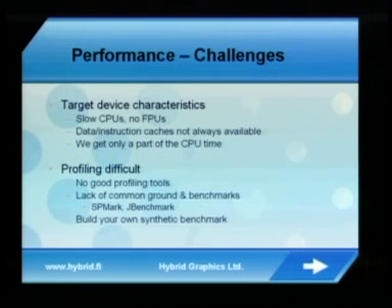The things that make it hard for us to provide a well-performing implementation are, first of all, slow CPUs. It's hard to make anything run fast on a slow CPU. In addition, we are also facing the lack of floating point units, which is pretty dramatic, because the OpenGL ES common profile requires you to support not exactly IEEE floats, but something comparable to that.